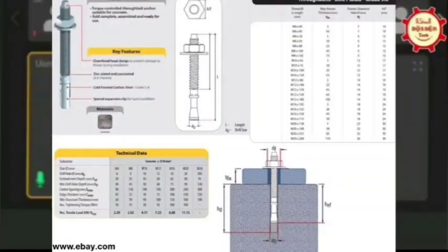Yeah, I have one more. In PV Elite, there is an option for anchor bolt calculations when we design a saddle. Normally, when we do it manually, it passes with a low bolt size, and in PV Elite it passes only with a higher bolt size. So which one is good?